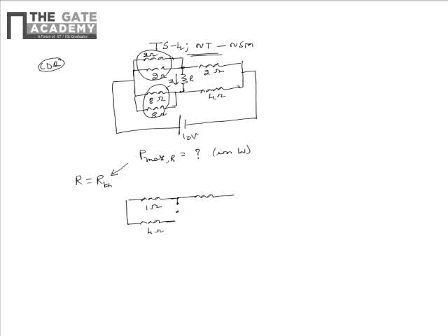And for RTH, as the circuit doesn't contain dependent sources, RTH is equal to the resistance viewed from the terminals of R. So R is kept open, and for finding the resistor value for maximum power dissipation, hence RTH, hence RAB, we know that RTH is equal to RAB, and for finding RAB, we need to replace the sources by their corresponding internal resistances.